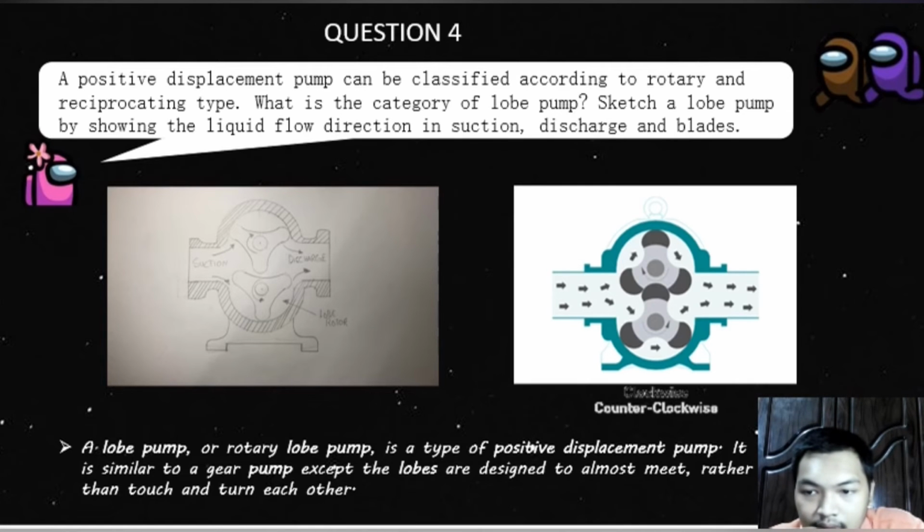How do rotary loop pumps work? Rotary loop pumps, which are self-priming positive displacement pumps, are not sensitive to dry running. The synchronous rotation of the rotor pair and the increasing suction chamber create a vacuum on the priming side of the pump. This vacuum draws the liquid into the pump chamber, and the pump medium is conveyed past the pump wall into the pressure area by the rotor.